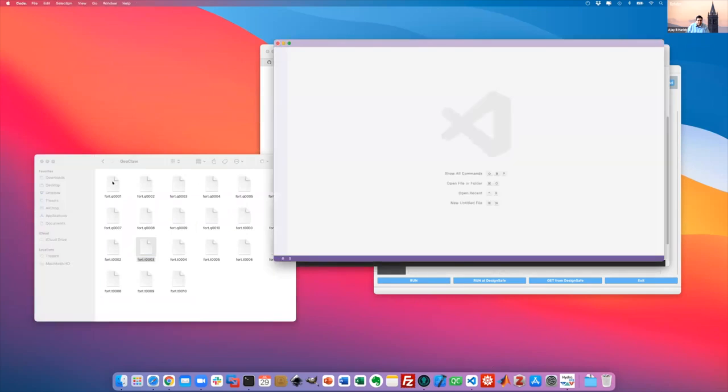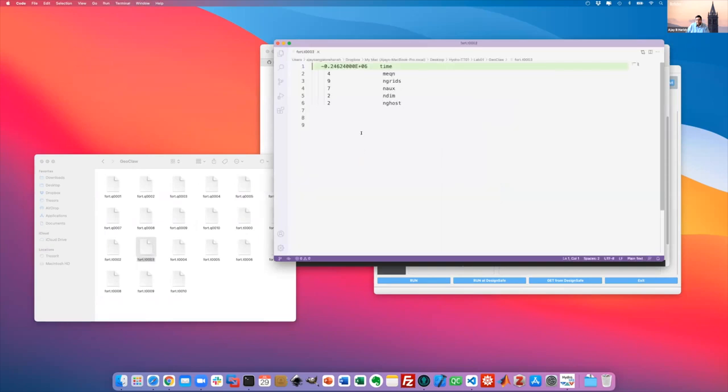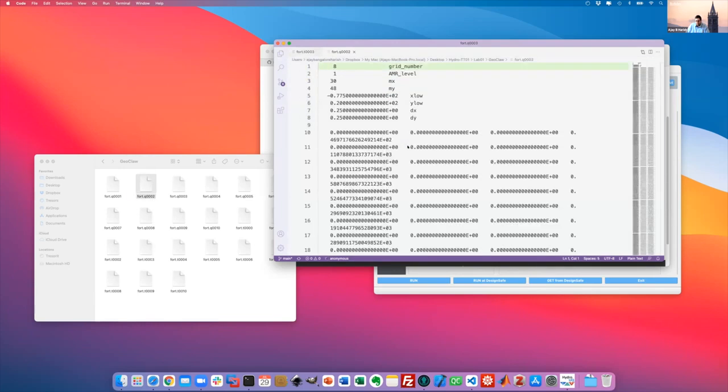So let's just open the file. 4.t has, as I think we went through in detail yesterday, the time information and the number of grids and the number of dimensions. These are most important to us. We already know it's a 2D shallow water solver, so you have the X and Y dimension, and you also have a number of grids. If we looked at this again yesterday, if you open the 4.q file of the output from GeoClaw, it basically has a grid number here, right? So when we say the 4.t.